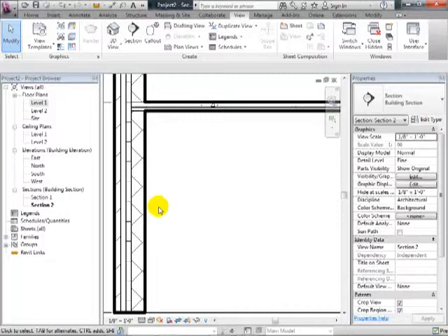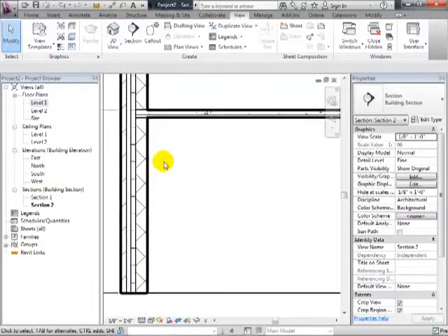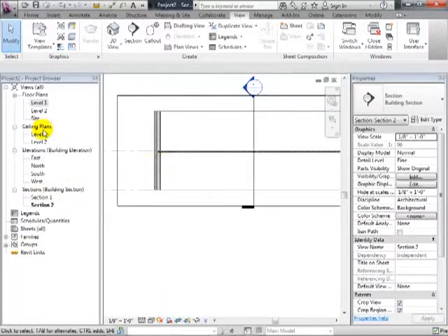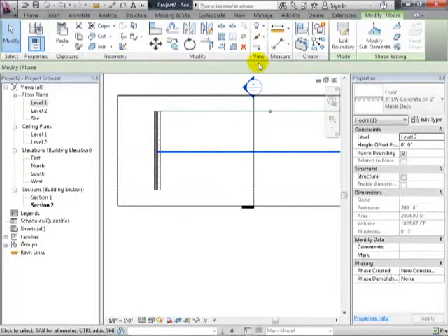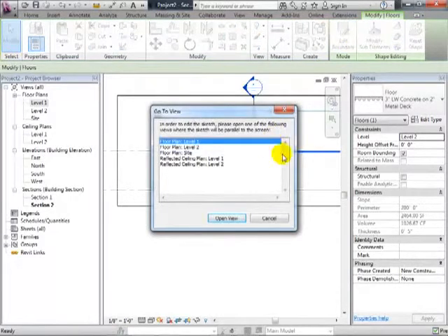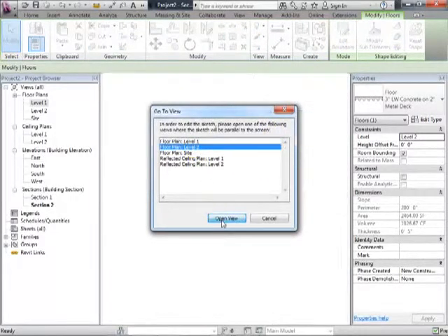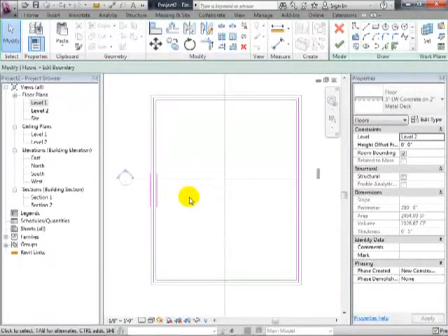Now, the direction those ribs run in is something you control back in the sketch. We don't pay much attention to it. But if I choose that floor, and again edit its boundary, I'll go back to the sketch. See those two parallel lines hanging around over here? These indicate the direction of the span of those ribbed elements.